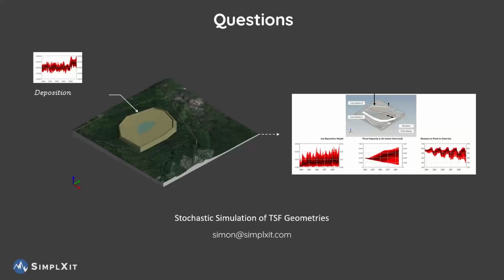Yeah, so in one of the examples that I showed, I think it might be this one actually, you can change whether you use a linear distribution or a compound slope. You can change those, and it's part of the Muk3D API, where within the code you can change both the slope and the distance if you've got compound slopes. But I think it's in the model that I showed towards the end that was included.